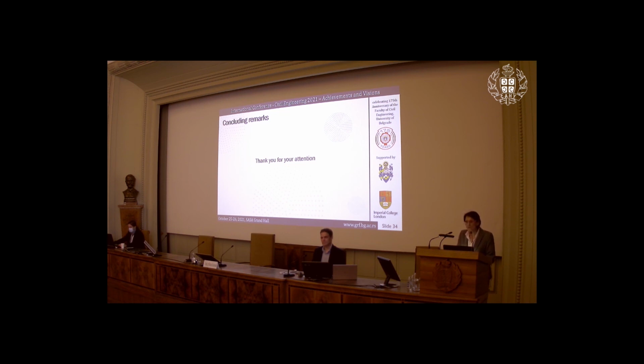With slopes, with anything that has to do with the ground, I think the main measurement is the pore pressures, the pressures in that void space, because that is where most of the movements are happening. For example, you excavate a slope, the initial phreatic surface depresses, and then with time it wants to go into some steady state equilibrium.